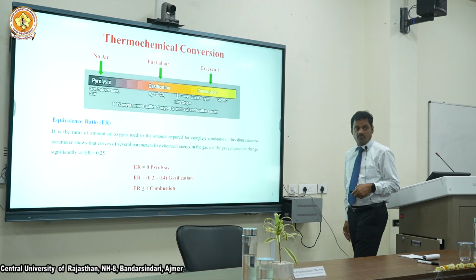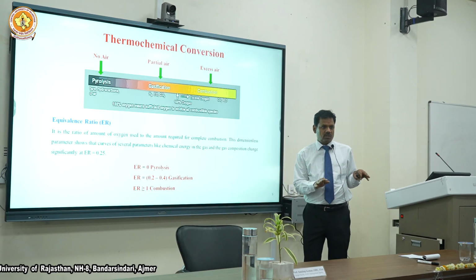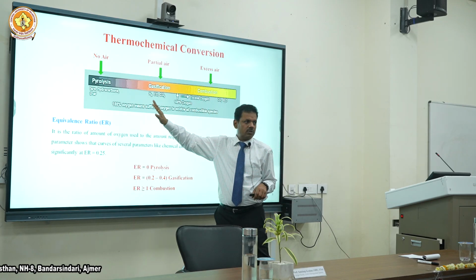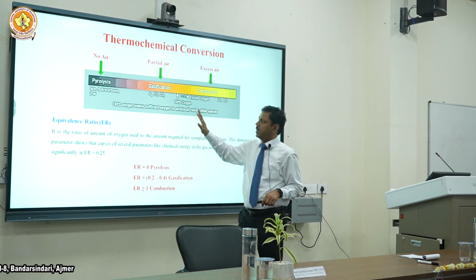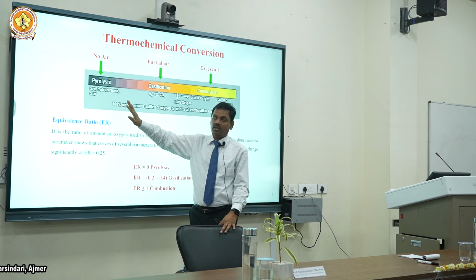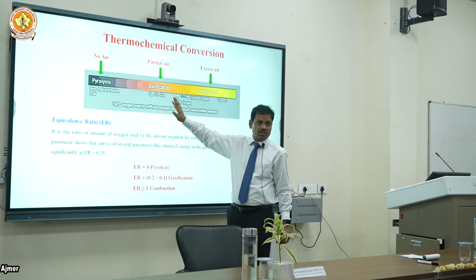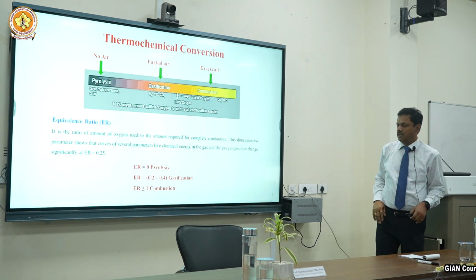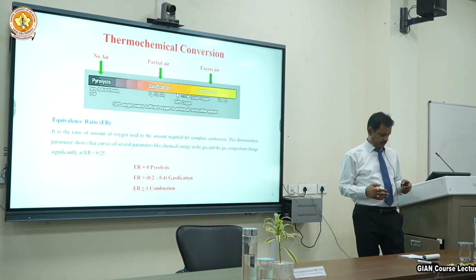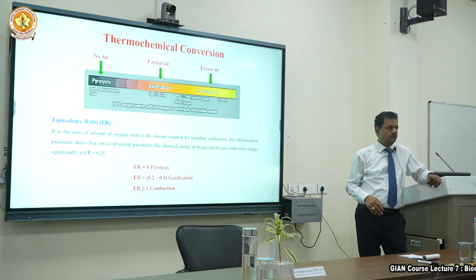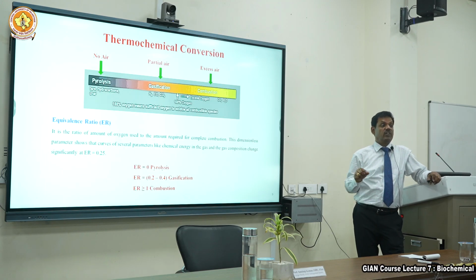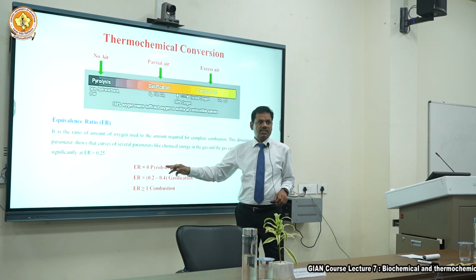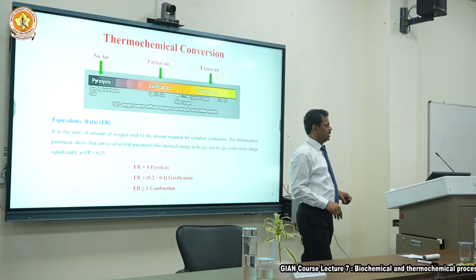So thermochemical conversion and hydrothermal are very similar. Let's look at the journey. We are looking at a scale. Pyrolysis is no air or no oxygen. Gasification is a little bit of oxygen and combustion is excess oxygen. How will we put this in numbers? That is called the equivalence ratio. For pyrolysis, the equivalence ratio is 0.